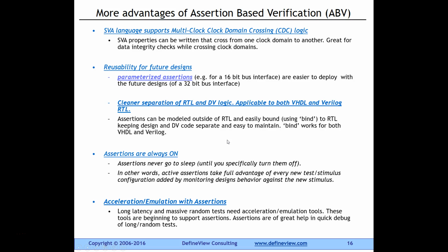And this is amazing because then whenever an assertion fires within the emulation box, for example, you can write to a debug register, and then you can, for example, boundary scan it out or ATPG scan out, and then you will know exactly where the design failed.